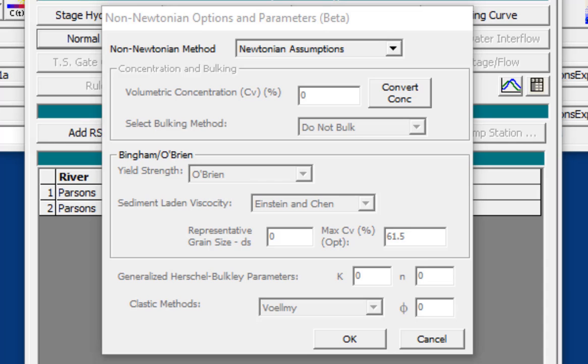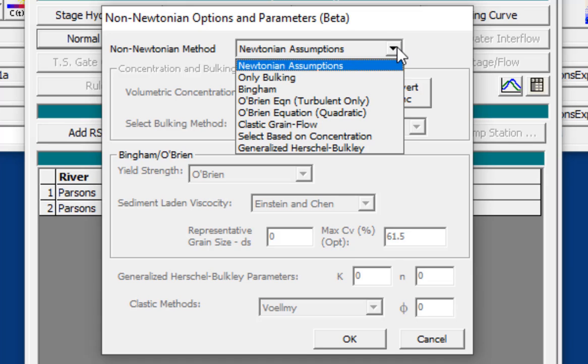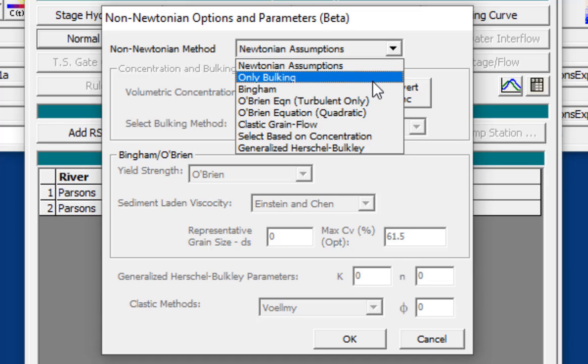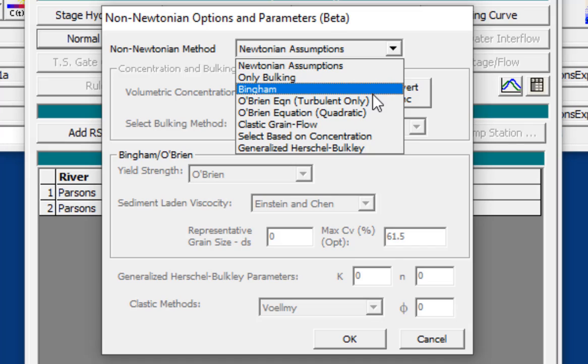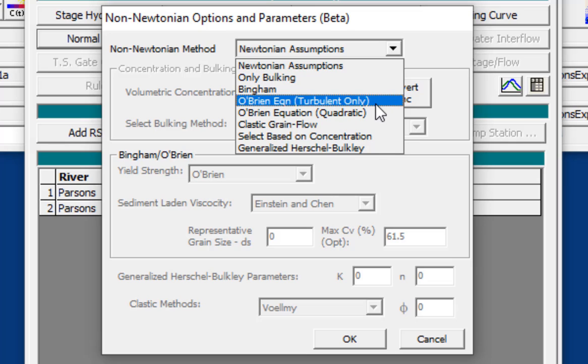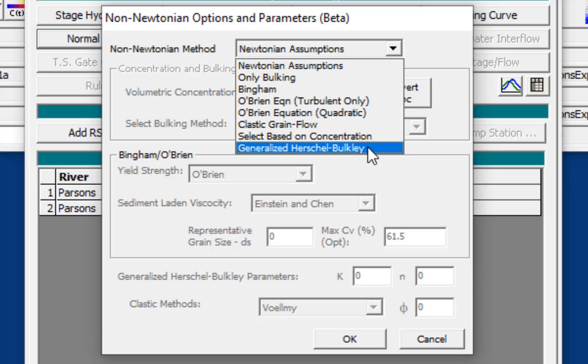Now if you click here, you'll see that we actually go into several of these in the paper. In the paper we simulate these experiments with turbulent dispersive and Herschel-Bulkley, and the RAS documentation will go into many of the other ones. This is all reaching to a non-Newtonian library called DebrisLib, which was developed jointly between HEC and ERDC Coastal Hydraulics Lab, led by Ian Floyd.